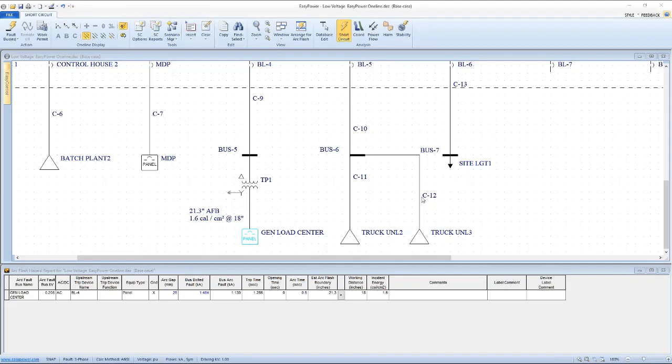So the next question, for the 208 volt panel, how did I come up with the 0.5 seconds for max time? In the application note that's in the handout section of the control box for this webinar, there's test results that IEEE reported that shows any arc, at least the minimum number of tests that they did, the limited number of tests, below 125 kVA and less than 240 volts, an arc could be initiated but would self-extinguish, and no arc lasted more than 300 milliseconds.